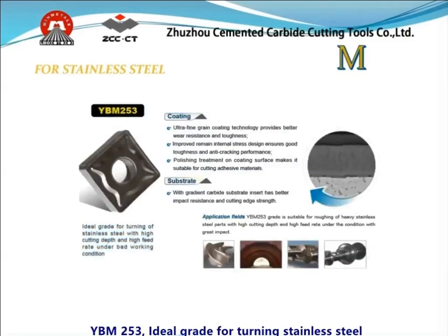YBM 25.3, the ideal grade for turning stainless steel, roughing or heavy machining with high cutting depth and high feed rate under conditions with great impact. The gradient carbide substrate improves both the impact resistance and cutting edge strength.